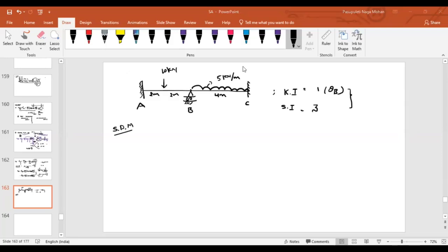How come the static indeterminacy is 5, Vishnu? How come it's 4, 3? If I neglect the axial deformations, how many will come into picture? Let us say I have neglected the axial kind of thing, because generally that's what we'll do. Here, how many will develop? Vertical, rotation, vertical, vertical, rotation, total 5 minus, as I already ignored axial, 5 minus 2, 3.